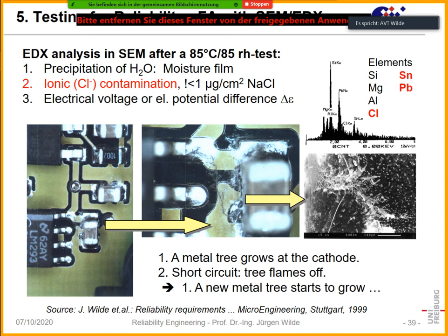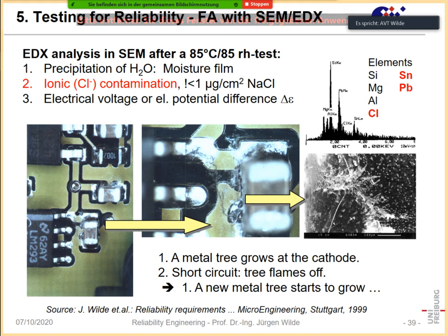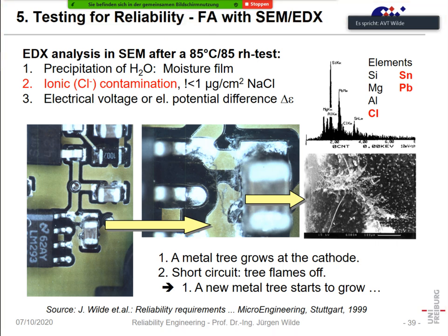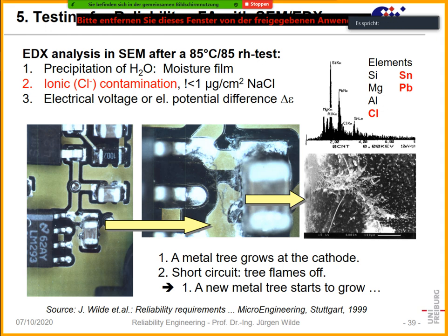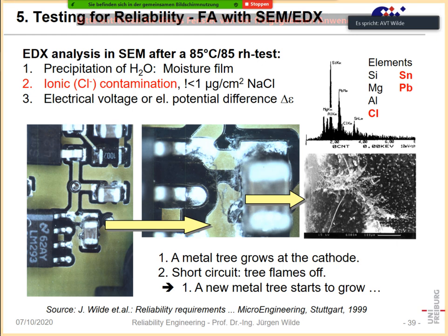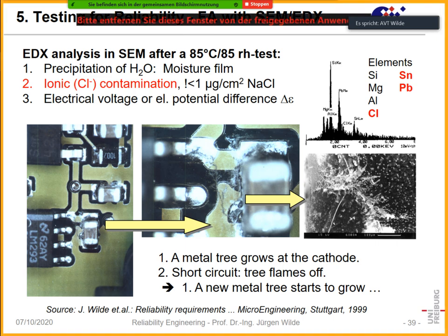So, strange thing, this led us to the knowledge, the know-how, that it would not be possible to avoid such coating of the ECUs. And so, after many years, ECUs are still coated after the soldering in order to prevent the deposition or precipitation of a very thin water film, which is deadly in combination with electrical potential and in combination with ionic contamination. So this could be cleared up using two very simple instruments, which are the light microscope and the scanning electron microscope in combination with an EDX.